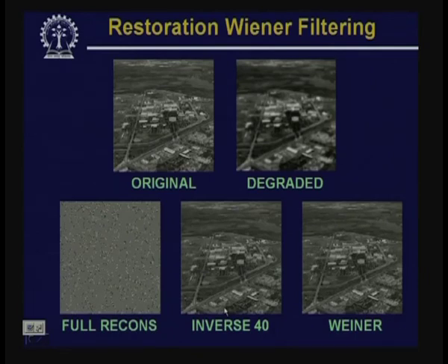However, visually they appear to be almost the same. The advantage of the Wiener filter is that I do not have to decide what extent of frequency components to consider for restoration of the undegraded image.